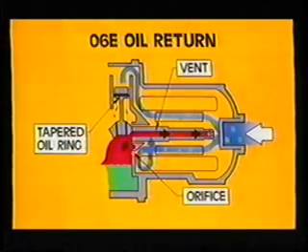A differential in excess of 2 psi indicates possible problems with rings, pistons, or valves. The orifice helps prevent a buildup of oil level in the sump on systems that are overcharged with oil. If the oil level builds up to the orifice, any additional oil returned past the rings to the sump will be pushed out through the orifice and put back into circulation.